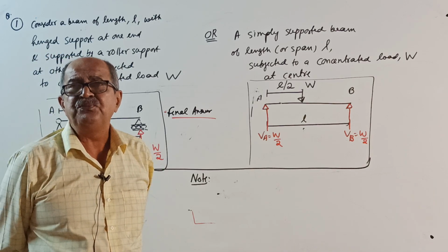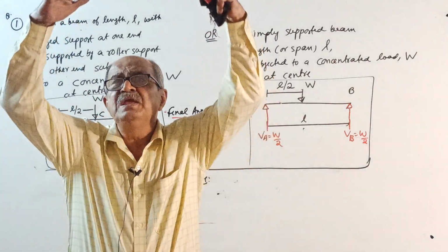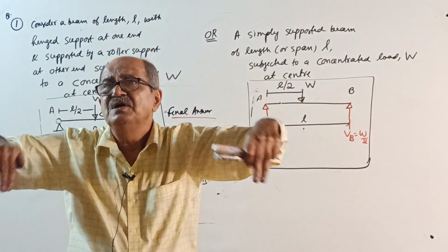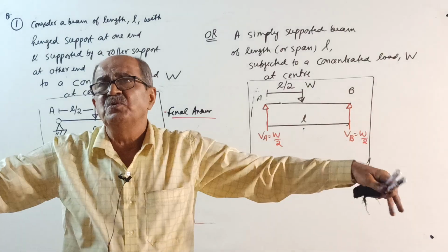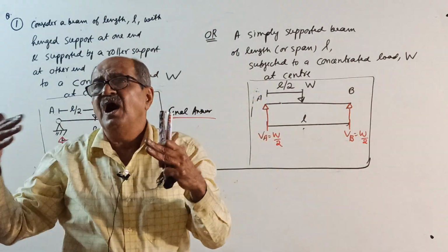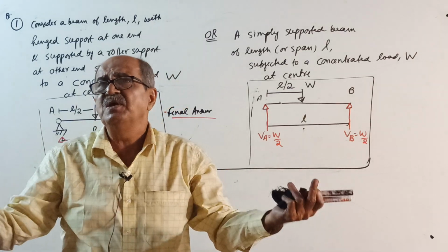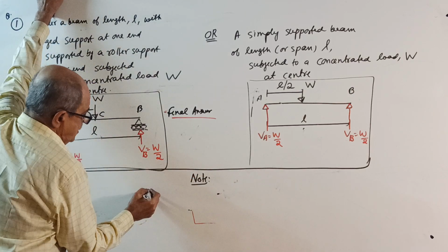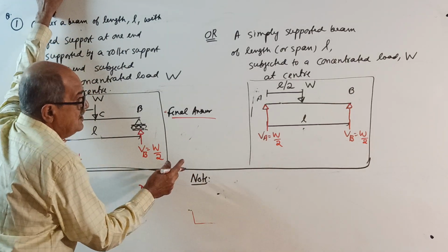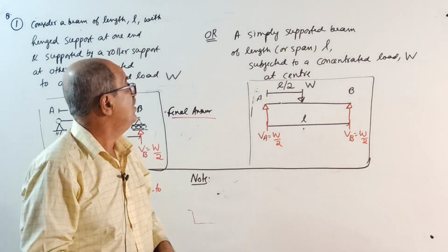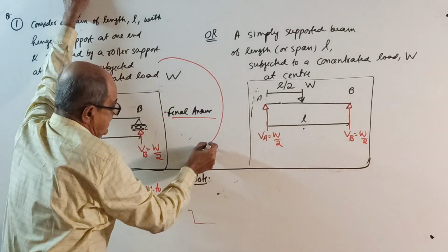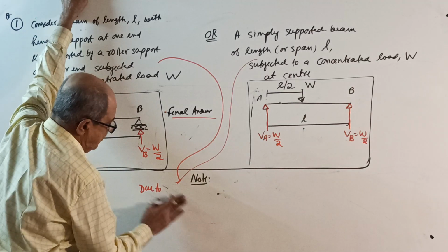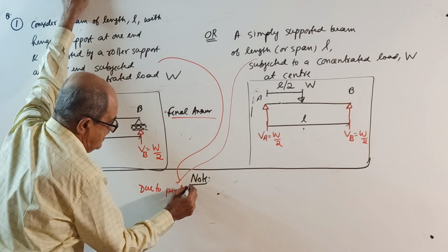This is a case of perfect symmetry. So, in case of perfect symmetry, whatever loading you apply on the beam will be transferred equally to the supports, or whatever load you apply, half the reaction at both supports will be equal to half of the total load. Very important, due to symmetry, you need not write sigma M0, sigma V0. This question, direct solution, due to perfect symmetry.